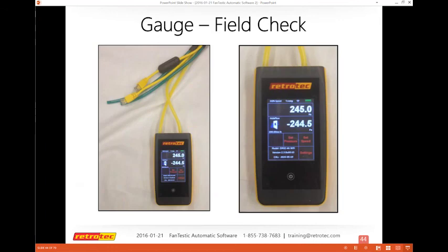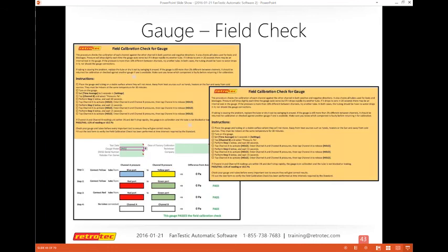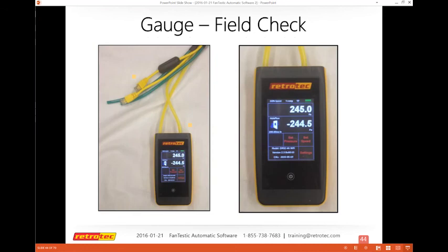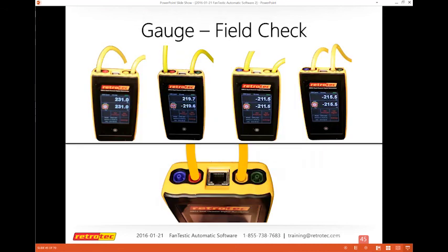There is also a field check you can download to fill out for your gauge, and it gives you basic information about how to connect the tubing, check the tubing, enter this form and your name and date, and you can document that you've been checking your gauge regularly. We moved to just using the yellow tubing with the umbilical because lower doors and duct testers all have one same common length, so it's easy to check your gauge and do that.